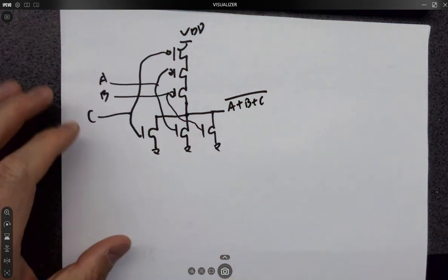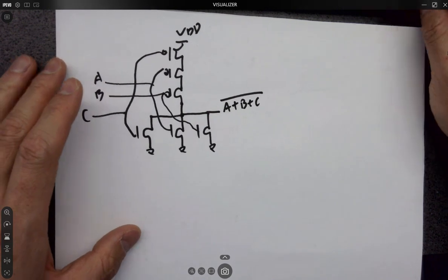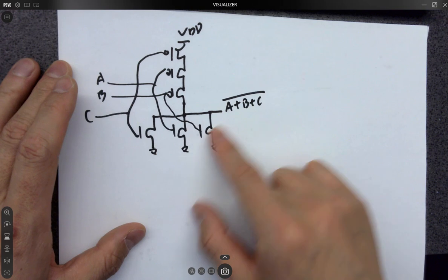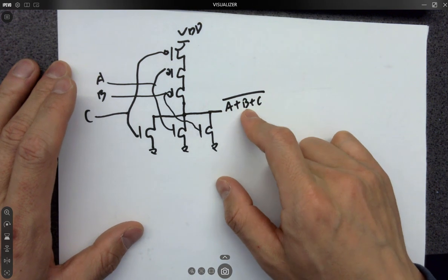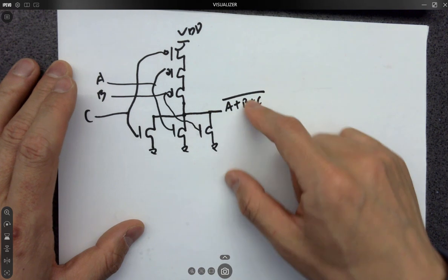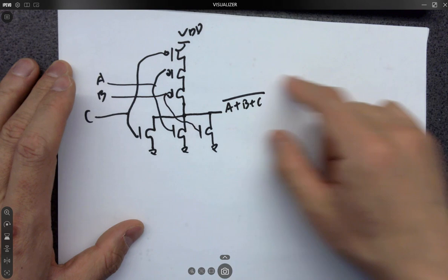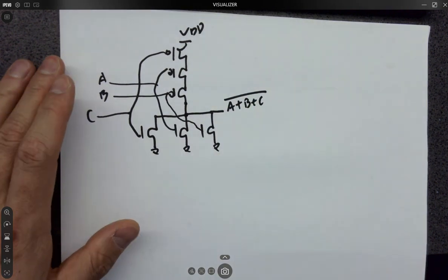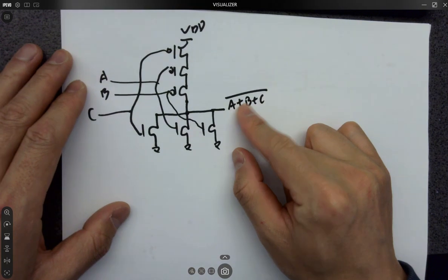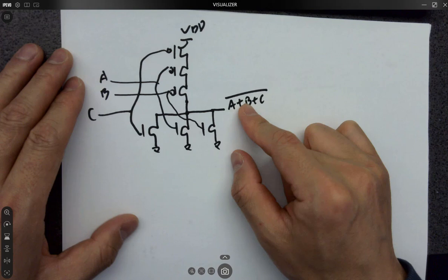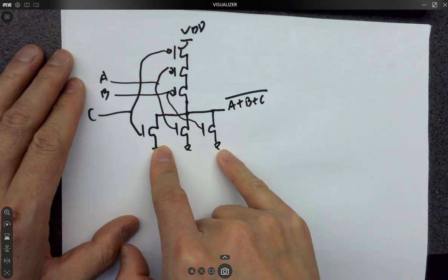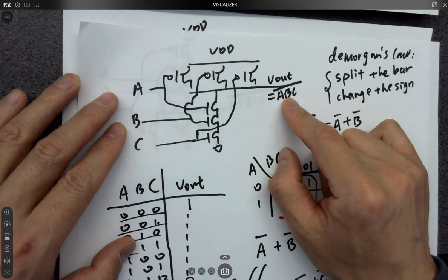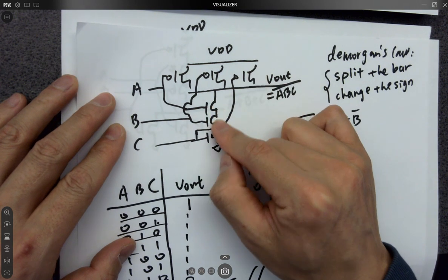And here comes the conclusion. First, for this type of circuit, it's getting inverted eventually. So you want to convert whatever logic expression into the form where you have a logic expression at the bottom and one uniform bar on the top, just one bar on the top. Then you look at the logic expression below the bar. If you have an OR logic, you should keep PMOSes in series and NMOSes in parallel. If it is an AND logic, you keep the PMOSes in parallel and NMOSes in series. That's the conclusion.